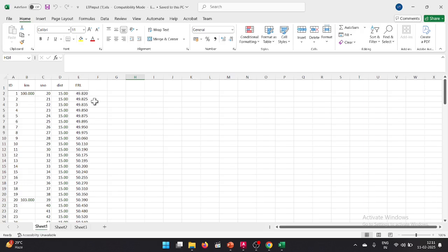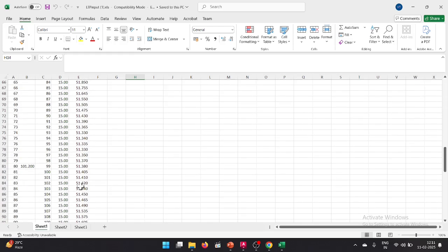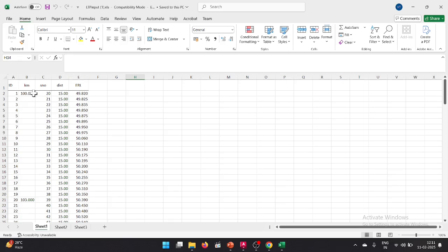Once you are feeding the level of each station here, you have to follow exactly this format, or you can download the copy, and without changing the format, you enter your complete data here, save it and import it. Here this Excel form I have used is the 2003 format, the old XLS format. Don't use XLSX. At present it will work only with the old Excel format.